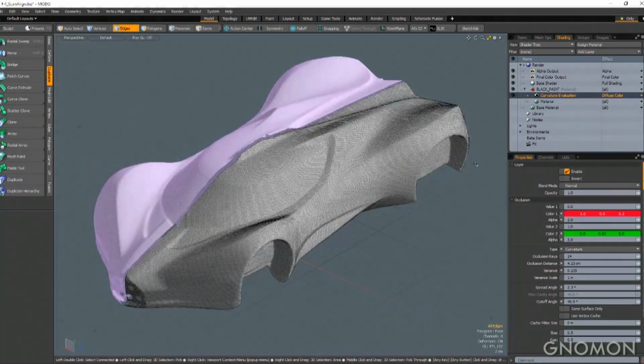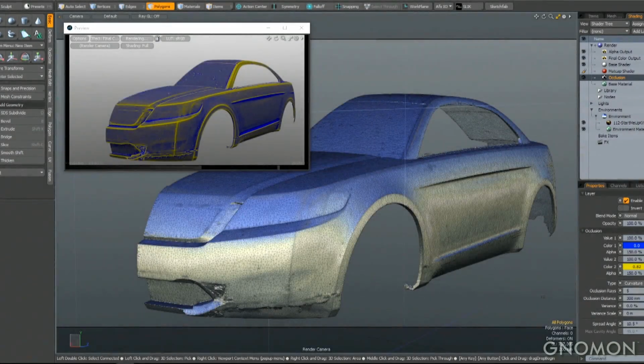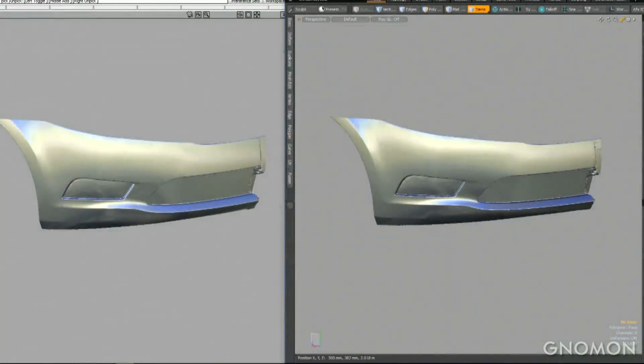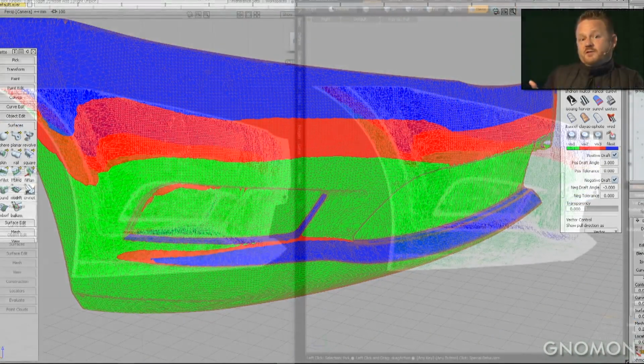So inspection tools, like looking at that clay: is it a good surface? Should we do it again? Those things are very valuable to the math modelers or creative digital sculptors. And sometimes guys just use a material capture or a ball map, or they use more of a procedural attack and look at the surfaces for the convexity and concavity. And being able to check for some sort of draft angle, like how good is the draft on this clay?